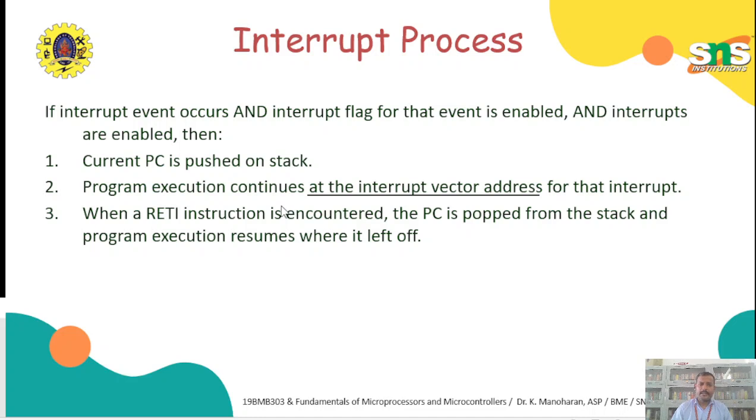Once the interrupt occurs, what happens? The current program counter value will be pushed onto the stack. Because we need to return to the main program, we need to have that address. That address is available in the program counter. So this program counter value will be stored to the stack.